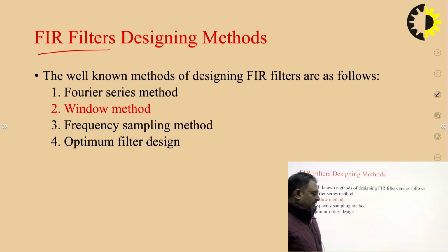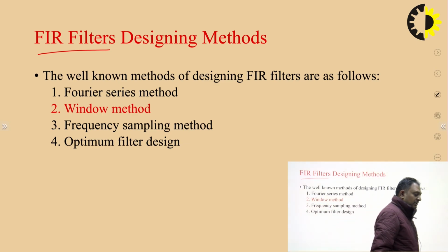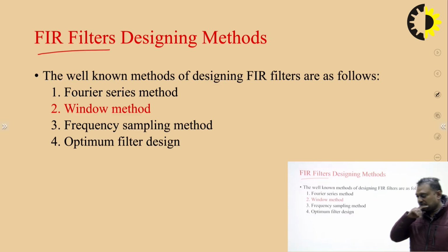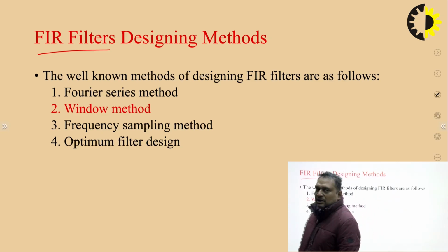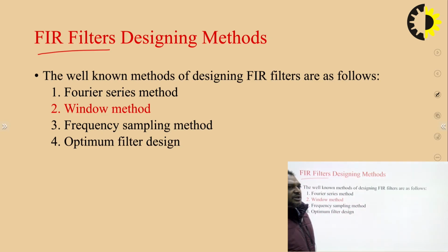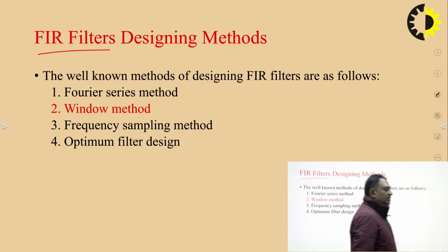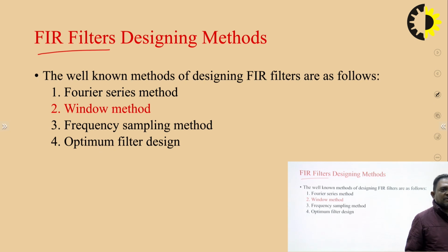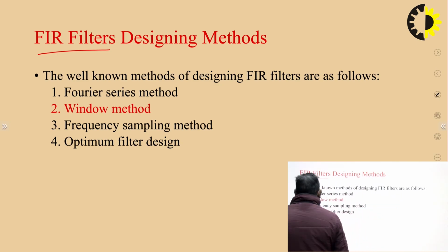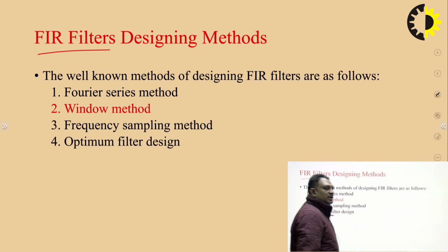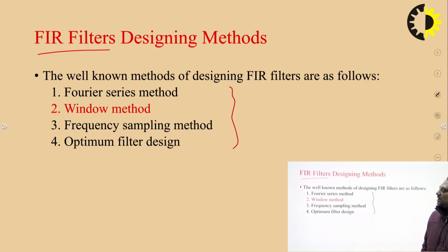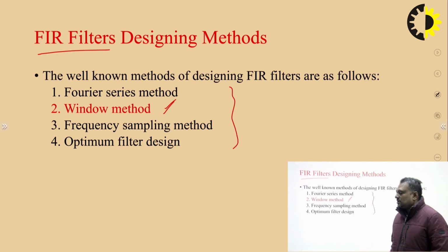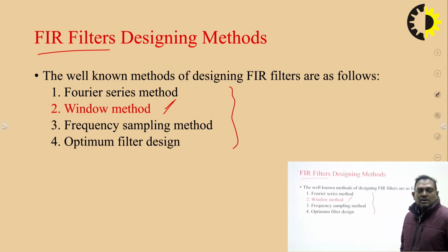Another thing is that FIR filters, if you talk about the realizing part, are realized using non-recursive techniques. And designing FIR filters is not so easy. This is a complex task, you can say. There are various methods by which we can design FIR filters. These methods are the Fourier series method, window method, frequency sampling method, and optimum filter design methods. Out of these four methods, we will concentrate here only on the window method, because this is part of our curriculum. So that's why we will see only the window method here.